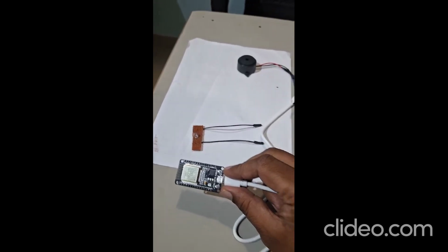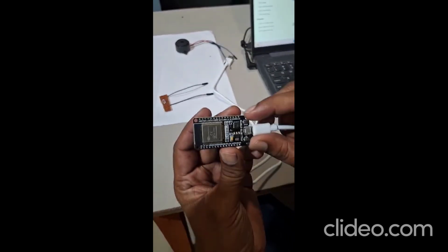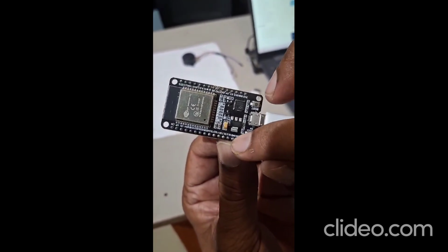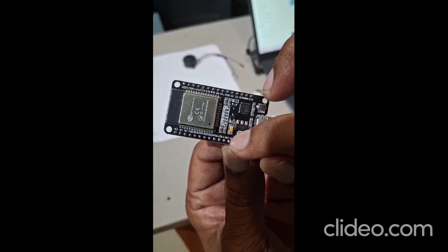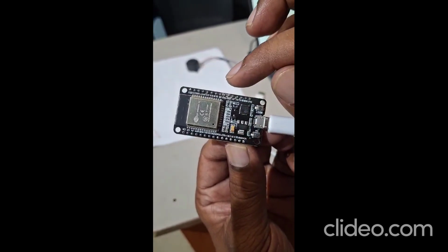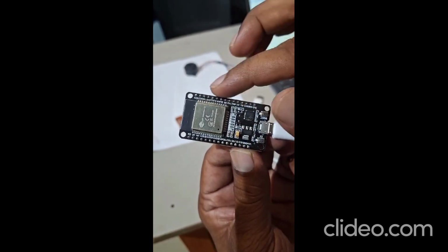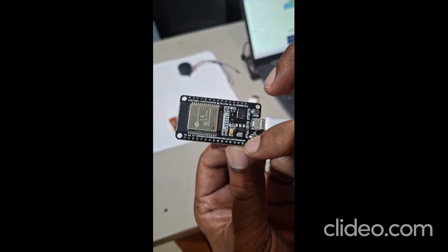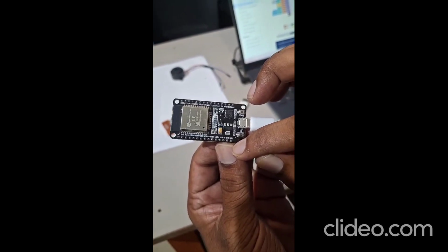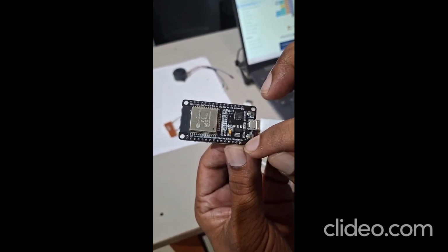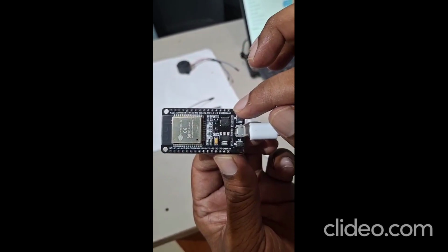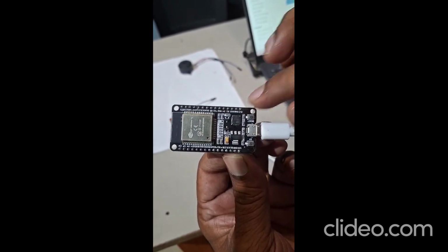This is ESP32. In ESP32, if you look closely, you'll find so many pins like V in, ground, D13, D12, D2. D written means digital input output. So you can connect your inputs or outputs wherever D is written. Anyhow, pin description will also be provided. V in and ground are there, so from there you can take the supply voltages if needed, like 3 volts or 5 volts or ground. From V in we can take 5 volts. Otherwise, other pins where 3.3 volts is written, from there we can take 3 volts.